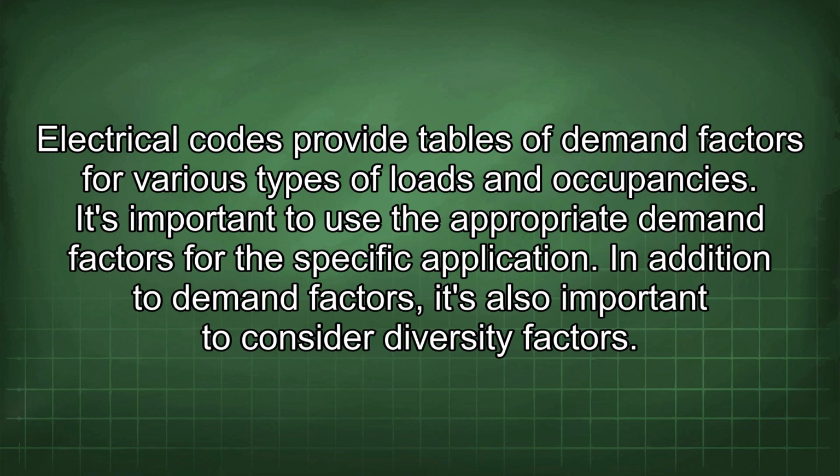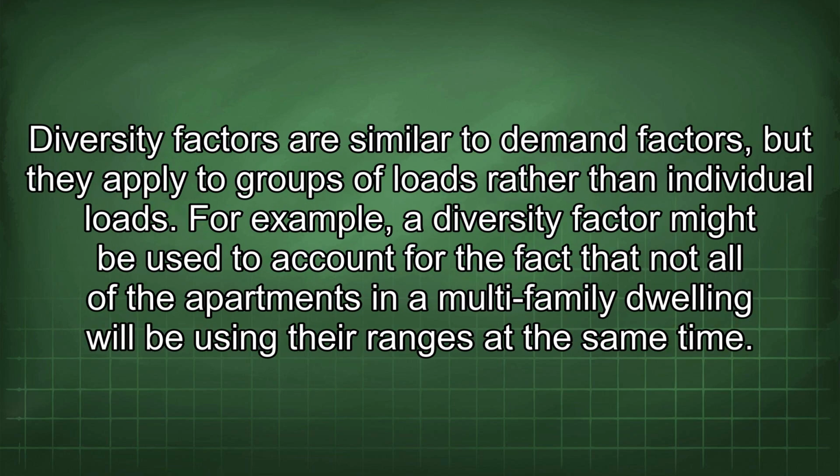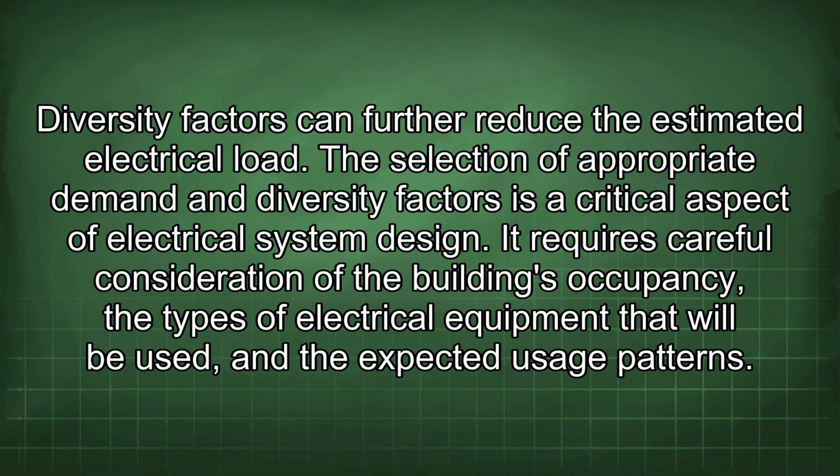In addition to demand factors, it's also important to consider diversity factors. Diversity factors are similar to demand factors, but they apply to groups of loads rather than individual loads. For example, a diversity factor might be used to account for the fact that not all of the apartments in a multi-family dwelling will be using their ranges at the same time. Diversity factors can further reduce the estimated electrical load.